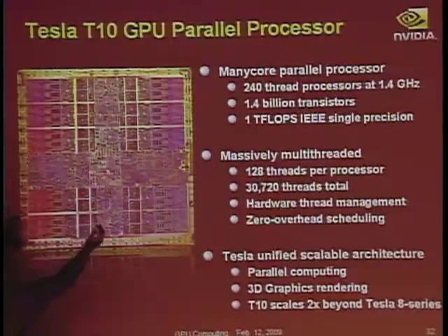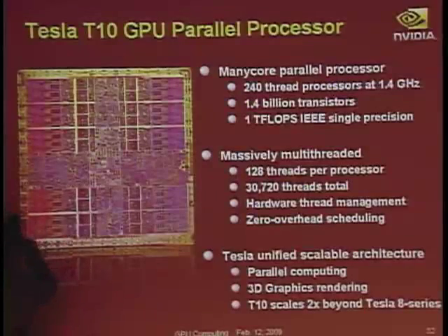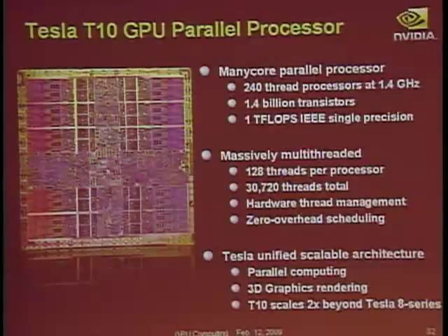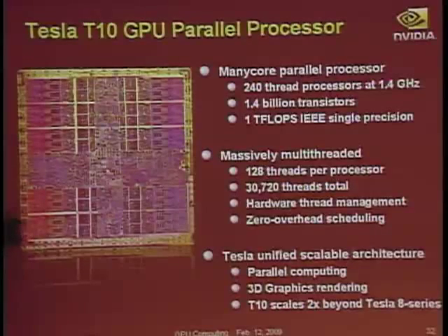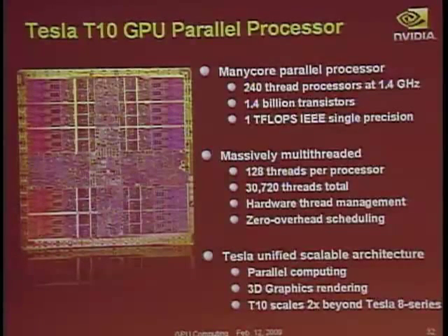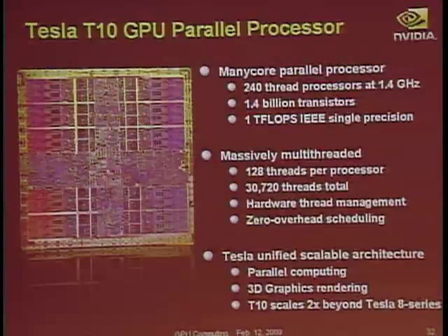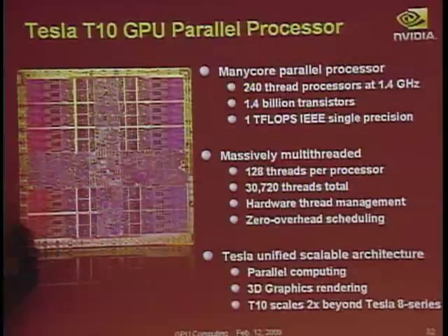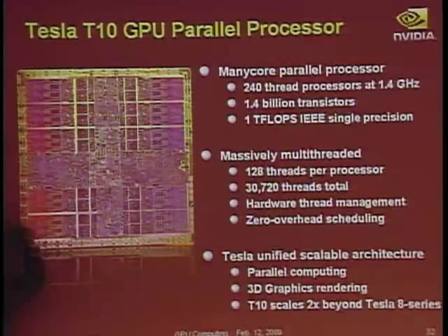So here's a cluster, and the cluster has 3 SM multiprocessors in it. So there's 3 times 8 is 24, so there's 24 SPs basically in this region here. So those registers in the middle stripe there? Yep, register file. And then the logic's on the outside? Yeah, so each SP is kind of a thin, skinny stripe this way.